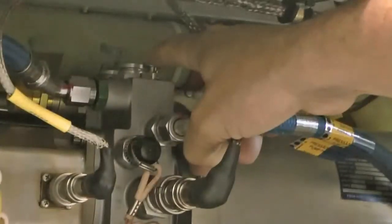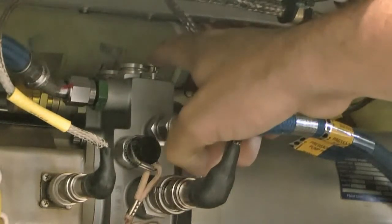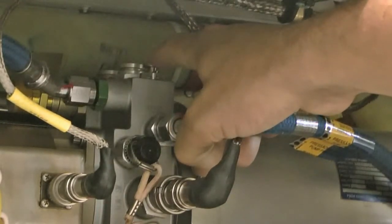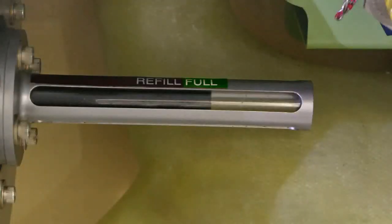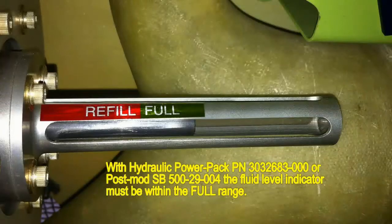Push the dump valve on the hydraulic power pack until all hydraulic fluid returns to the hydraulic reservoir. On the fluid level indicator, make sure the fluid indication is within normal range, within full scale. If the level indication is outside the full mark, contact maintenance personnel for hydraulic fluid servicing.